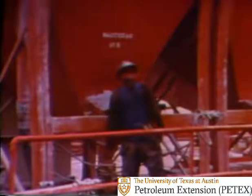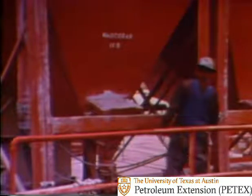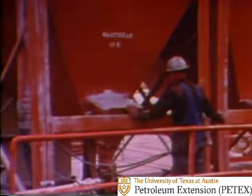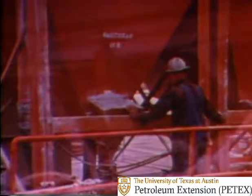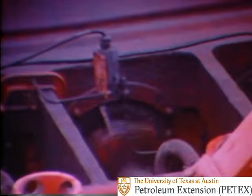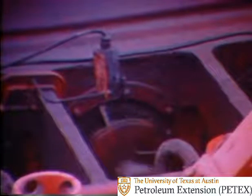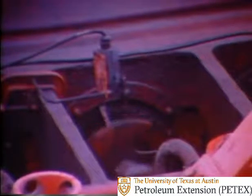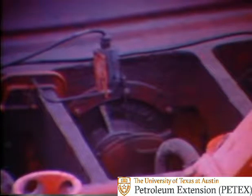As the kick is being circulated out, the crew prepares one or more pits of mud having the weight that was calculated to balance out the formation pressure. With the kick circulated out, the second circulation is begun using the heavier mud, and the same reduced pump speed as used previously.